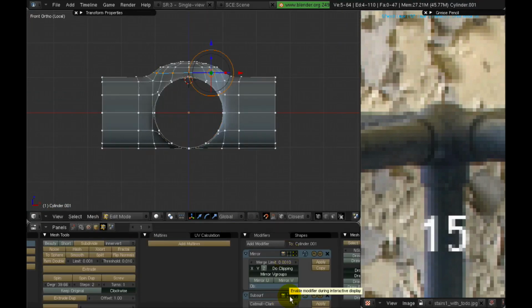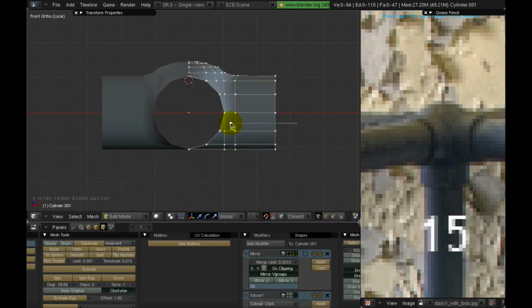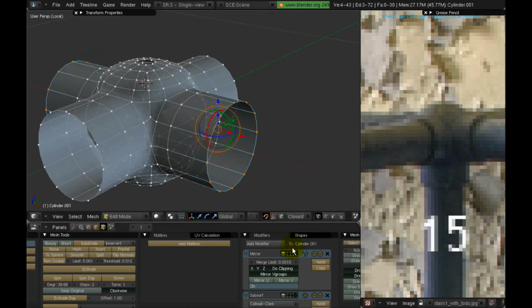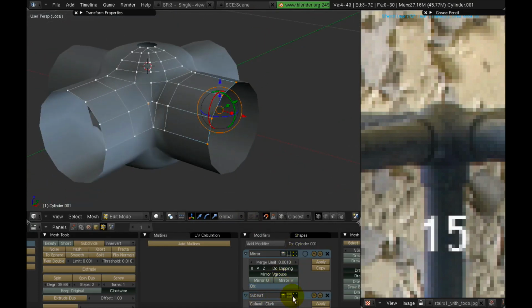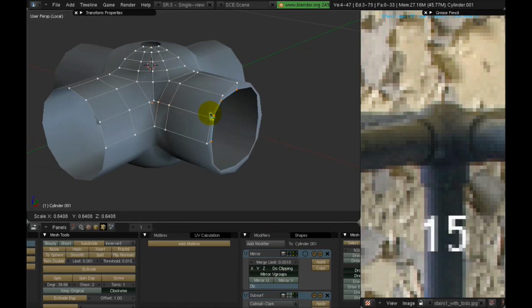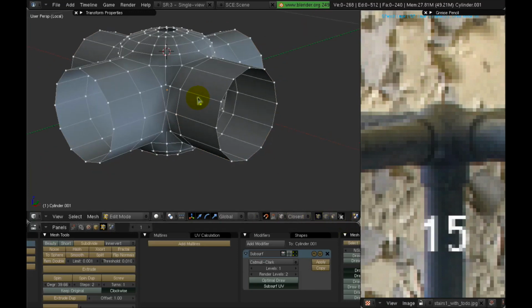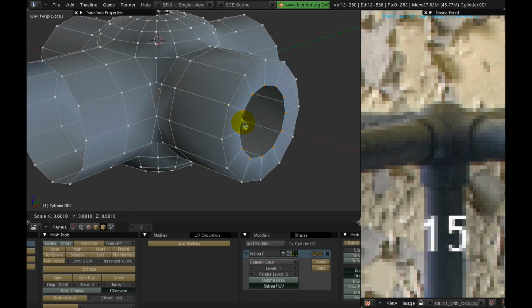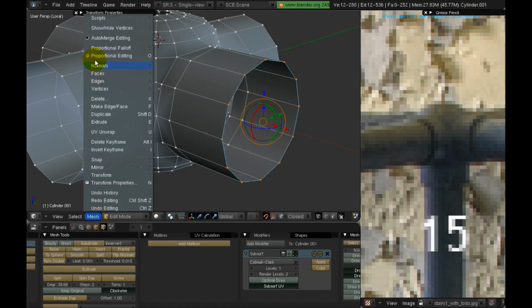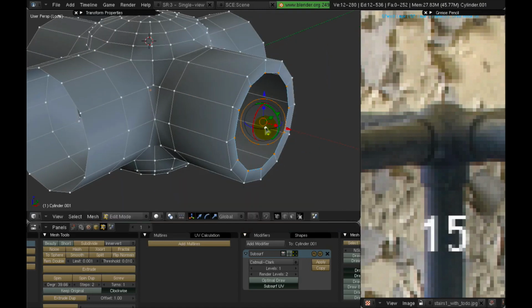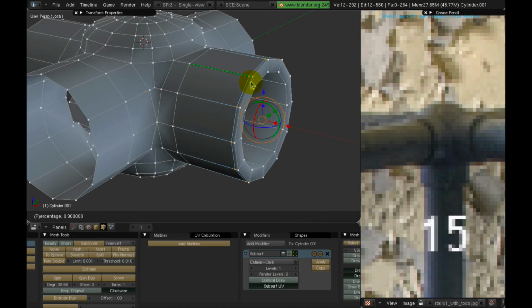Again, taking a look at our reference. And we want to delete the bottom part and add the Z-axis in our mirror modifier interface. And now we want to create the actual thickness of the openings. So let's first apply the mirror modifier so we can select the entire loop. And when we press extrude, we want to scale holding the control key down until we see a value of 0.8 in the lower left-hand corner on the header bar.